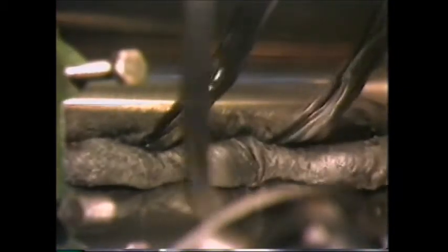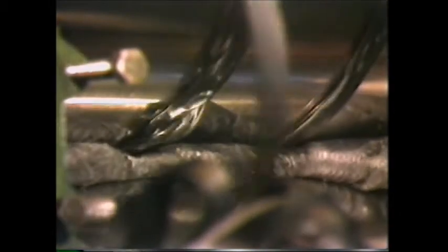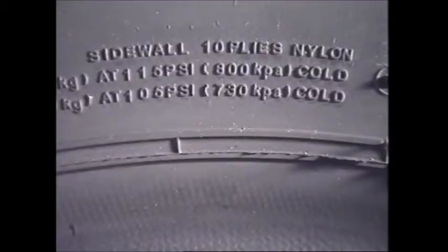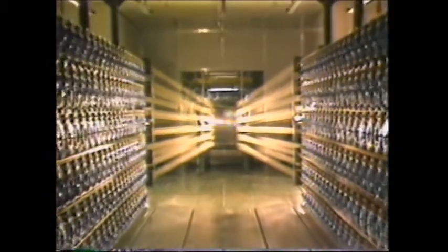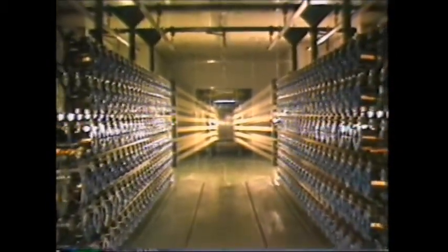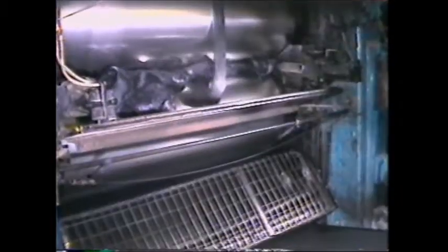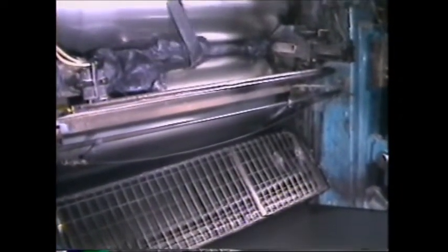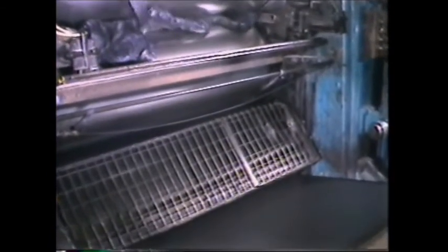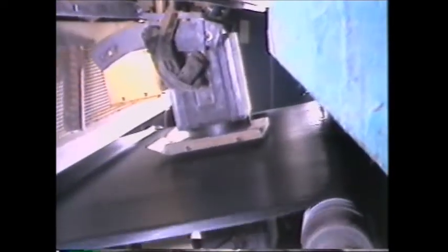The plies are made from cords of fabric coated with rubber. Early tyres used cords of cotton, but with increased vehicle speeds and loads, rayon and nylon cords are now common. Cords of synthetic fabric have high tensile strength. They resist stretching, but are flexible under load. The cords are placed in parallel and impregnated with rubber to form sheets called plies. Plies have high strength in one direction and are flexible in other directions.